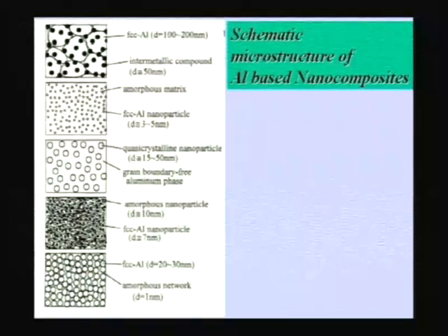So, you have crystalline aluminum grains, and into which you have crystalline Al3Ta particles or any intermetallic particle. Al3Ta is one example. You can have Al3Ta, Al3Fe or any type of intermetallics, or nickel aluminides, for example. You can have aluminum matrix and nickel aluminide particles in it. Or for example Al3Li, if you can make it into nanoparticles, you can have Al3Li nanoparticles in an aluminum matrix, though not many people have tried that kind of thing.